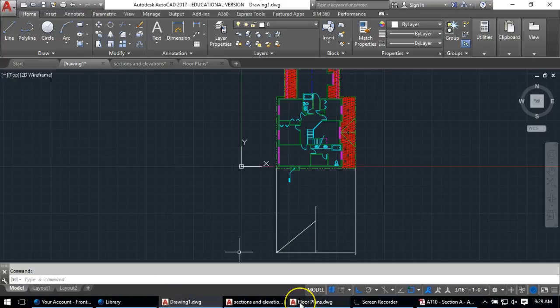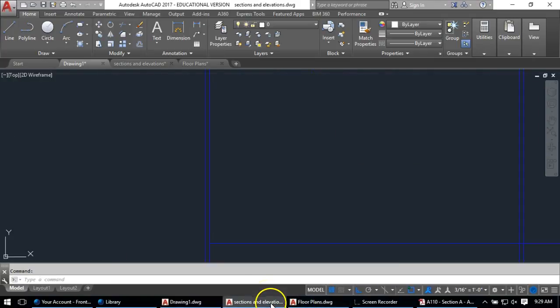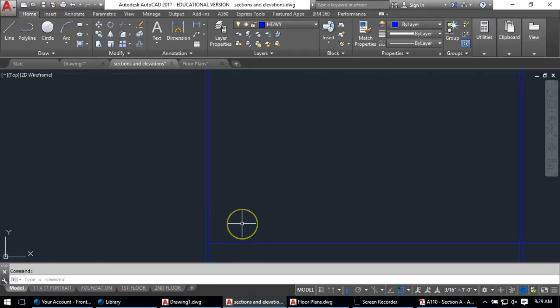Now I can start to offset that distance, but again, it's not offset from here. I first got to offset my half-inch drywall, right? And then I've got this truss here, which again, we don't really know the details of until we draw section B, but I believe those are 2x6s as the bottom. So I'm just going to strike a line. It's not a line we need, it's just going to be a guideline, but I'm going to go up 5.5 inches, which is going to be the top chord of my truss, because from that point up is where the roof takes off from.